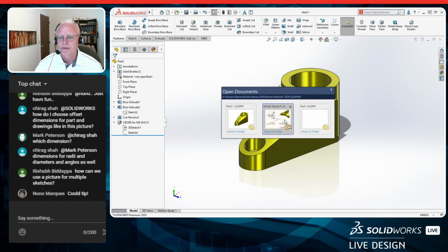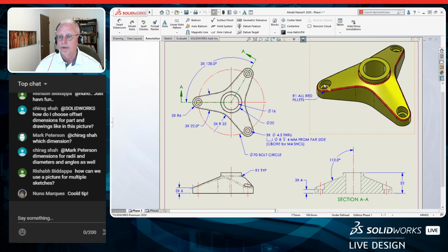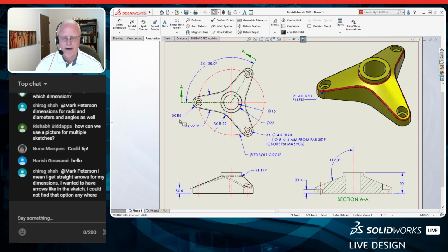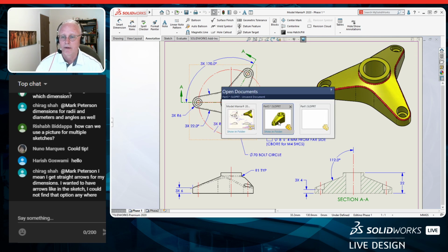So come back to our drawing here, see what we got. We have 3 of these. We got our counterbore hole in. We don't have our fillets on. I always say fillet late, fillet last, or fillet late, draft early, fillet late. These 22 millimeter radii, I can't get in there until later. So let's go ahead and do our patterning, and we'll put our 22s in and then those on, and I think we're kind of good to go here.